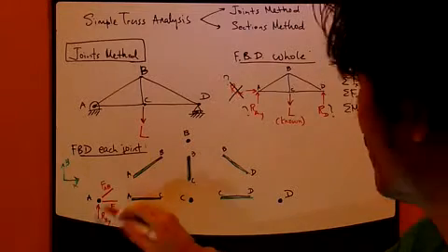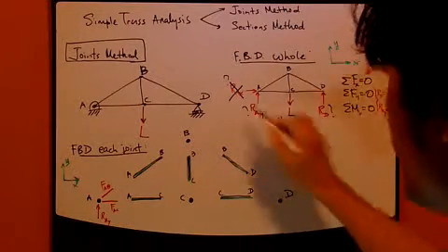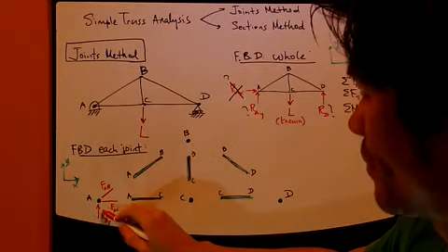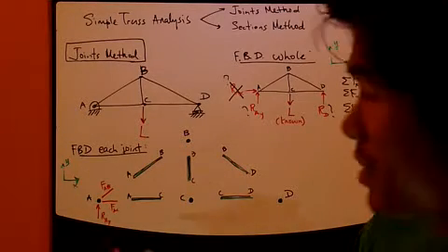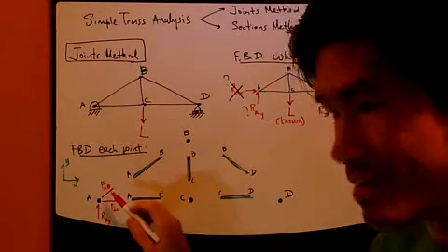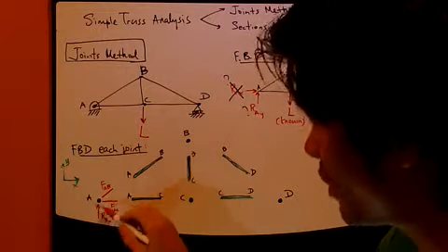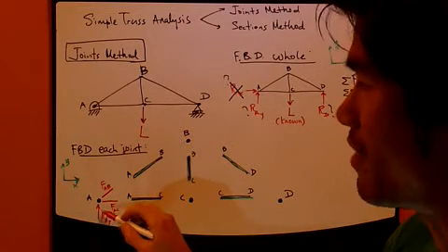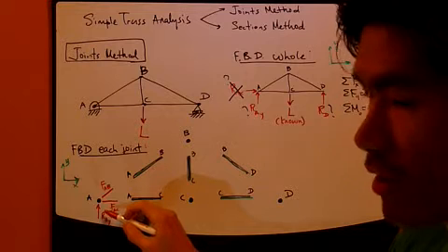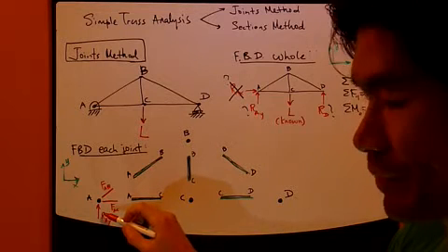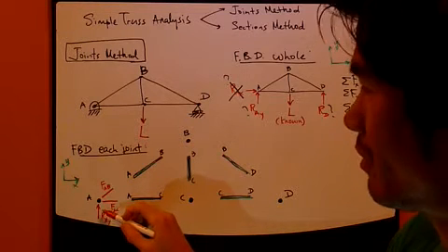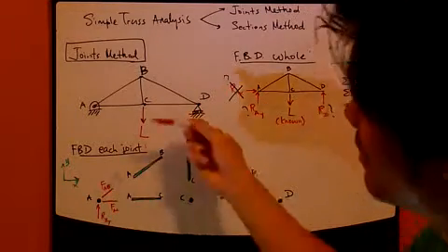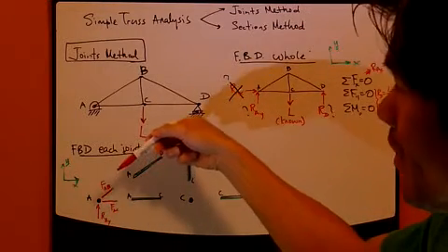You do know that from the free body diagram for the whole bridge, the whole truss. So this goes up, you know. This means that something else must come down to counter this RAY. And the only possible downward force is coming from FAB, because FAB is slanted.